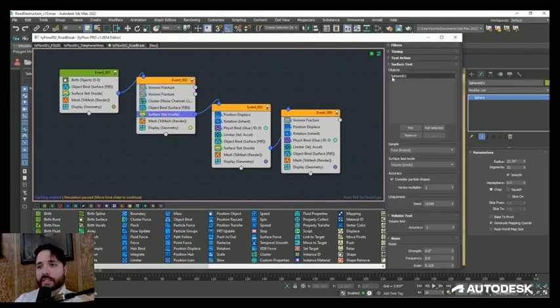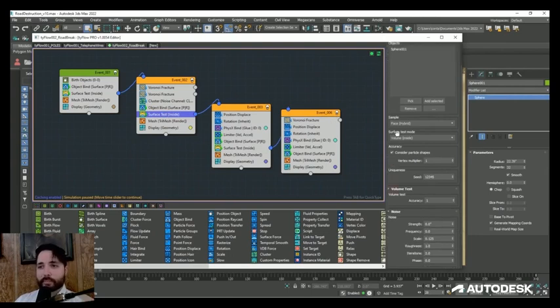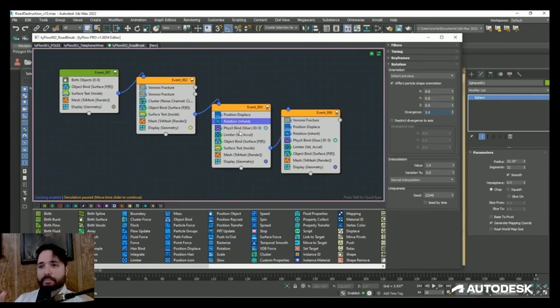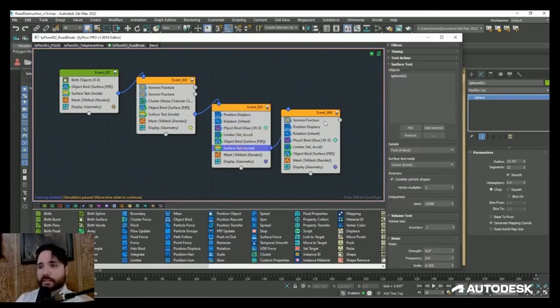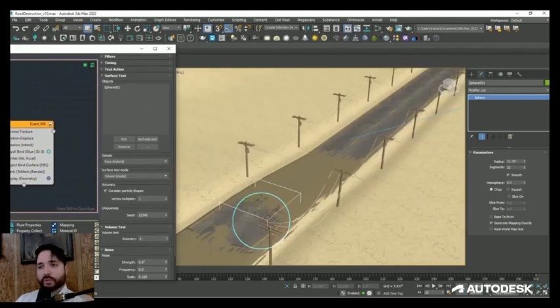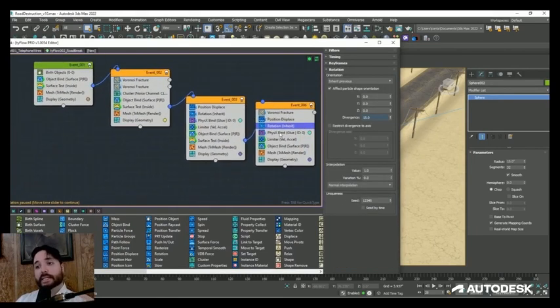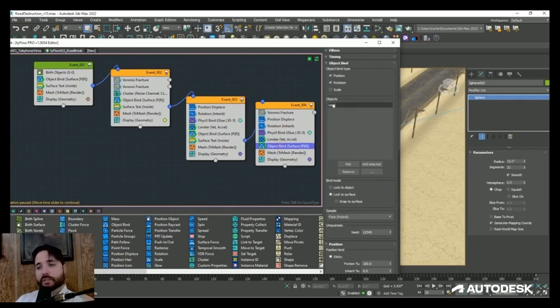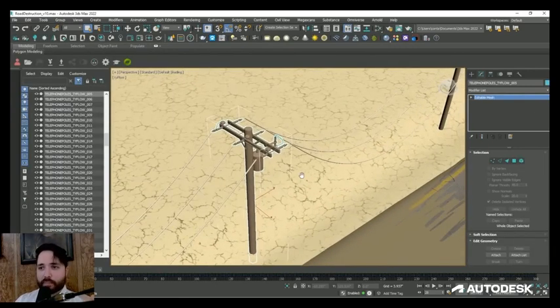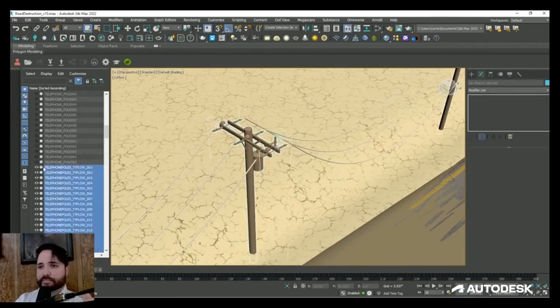I made sure to continually add object bind operators to each event so that as our desert mesh rippled across the landscape, the fractured road particles would still stick to that surface. The smaller secondary sphere collider was trailing slightly behind the larger sphere object, and it was used to trigger the fourth TyFlow event, where the road chunks were fractured for a second time. And I also made sure to include the position and rotation operators in order to help displace the particles and make the asphalt look like it was cracking as soon as the particles entered that event.